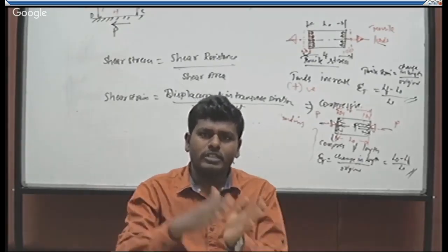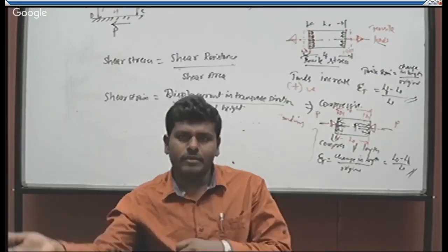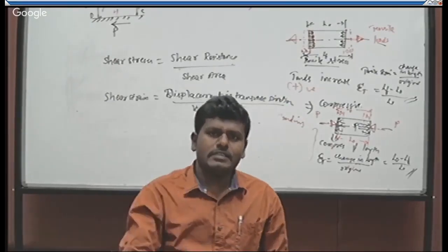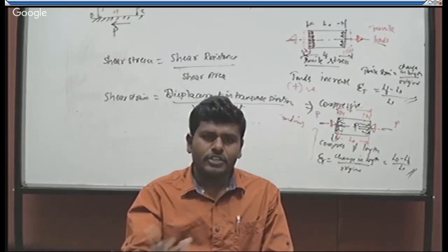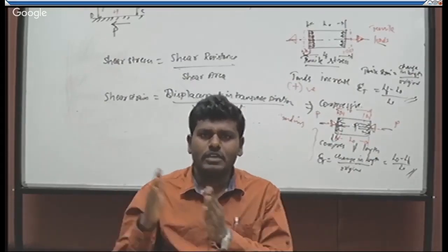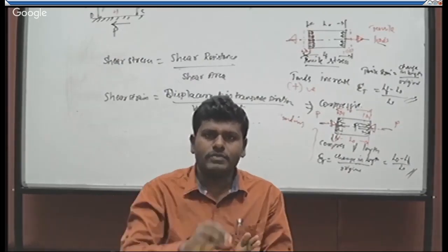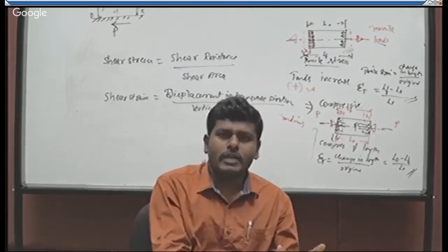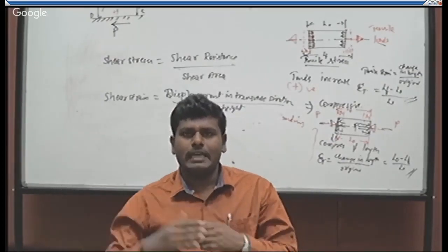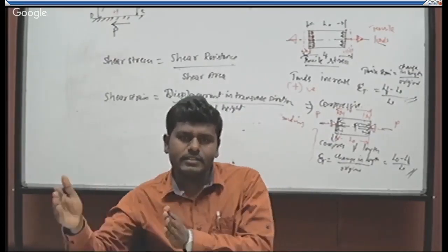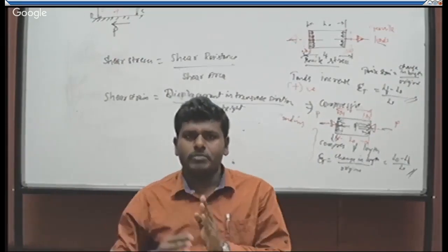Beyond that limit, if we further increase the load or the rate of stress induced, then the deformation occurred due to that value of stress will not come back to its original size and shape. It goes to the plastic state, or it retains its deformation permanently.